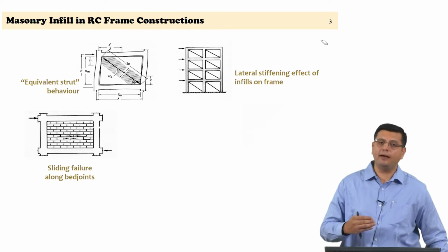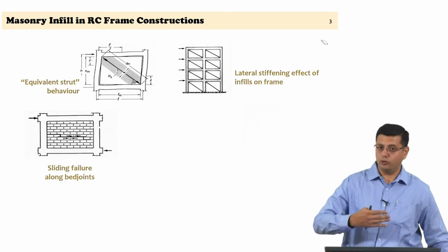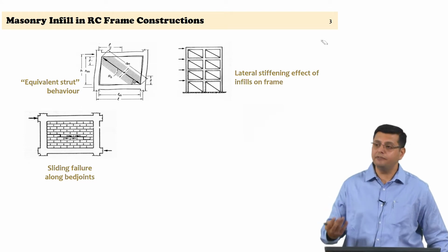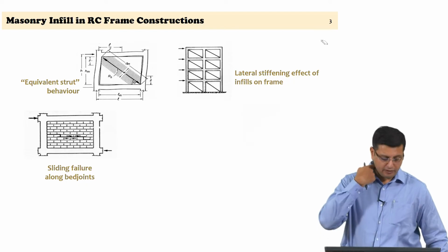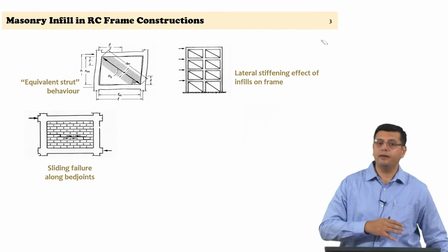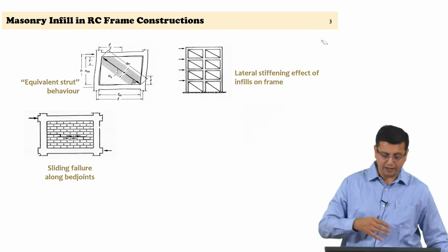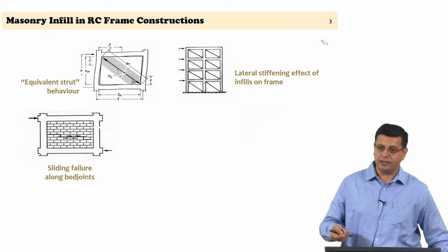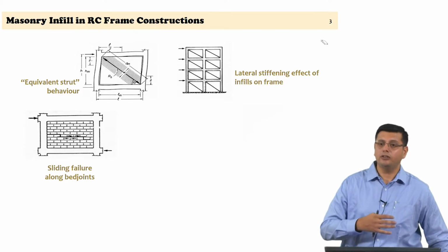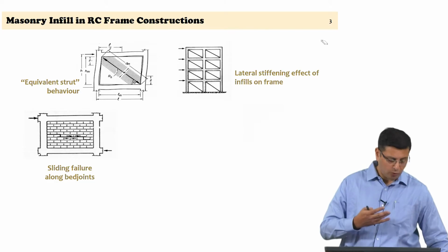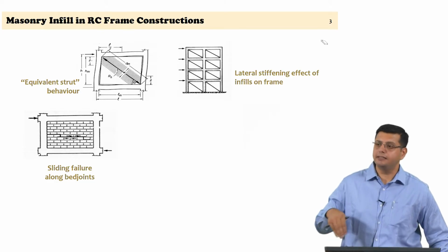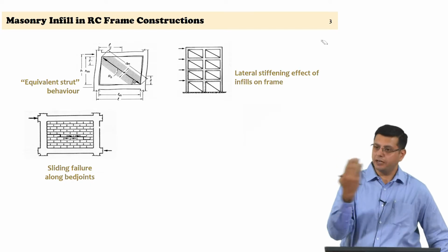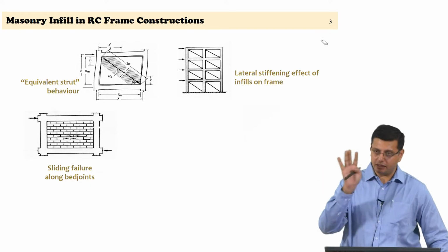We have seen how an unreinforced masonry panel when subjected to lateral forces can have different failure mechanisms depending on the overall geometry and aspect ratios and the different material strengths, be it the compressive strength of masonry or the joint shear strength or the tensile strength of masonry itself. So, similarly different failure mechanisms can be expected in the infill panel, which is really an in-plane shear wall, however sitting within a frame.